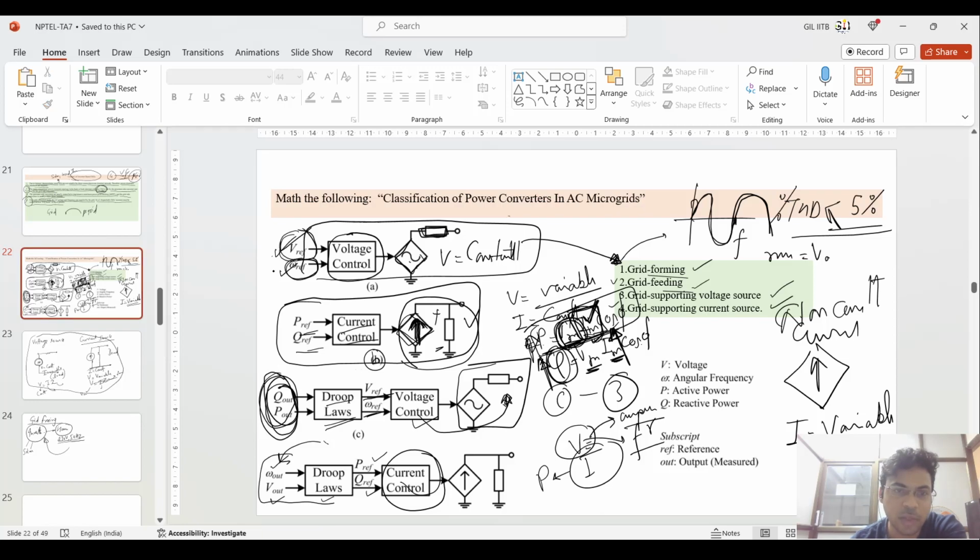Okay, so the difference I explained in the voltage and frequency: in the grid forming image, the voltage is based upon itself. You take the V as a voltage and frequency reference, because at forming the grid you control and maintain the voltage and the frequency at a constant level. Because at home you connect 50 appliances, 100 appliances, the current is varying but the voltage is constant. You can increase the current. And in the second figure, what I have showed you, here it says that suppose this is a current source.